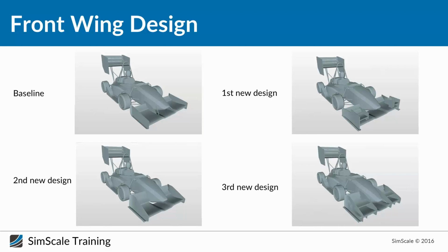Yes, that's right. It will be very much a case by case. It will depend on where the tire is relative to the front wing. These tires are quite small on the Formula Student, so it would be interesting to see if these cascade elements will work as they do on a Formula One car, and maybe they wouldn't. So it's something that we'll have to check in CFD.